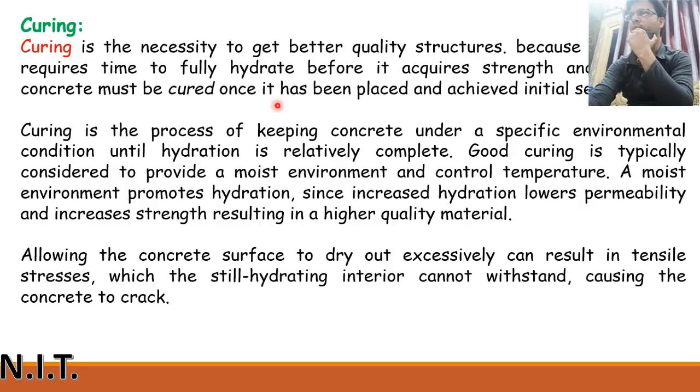Concrete must be cured once it has been placed and achieved initial setting. When the initial setting is achieved, concrete should be cured. And curing can be done for different time periods. It can be 7 days, 14 days, 28 days. It depends on the project requirements.